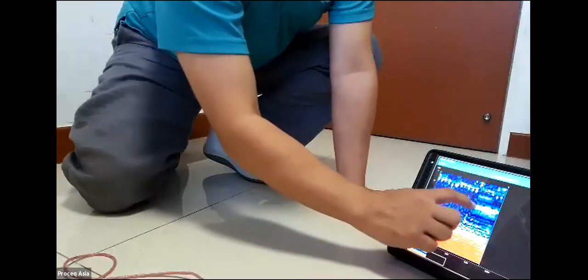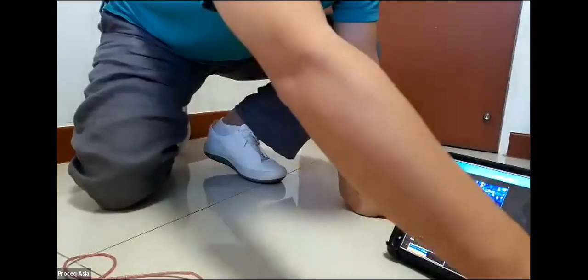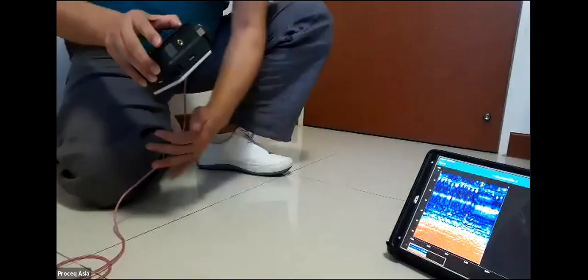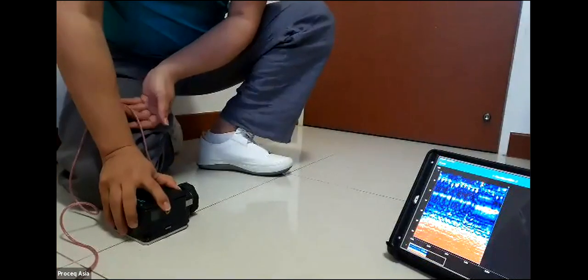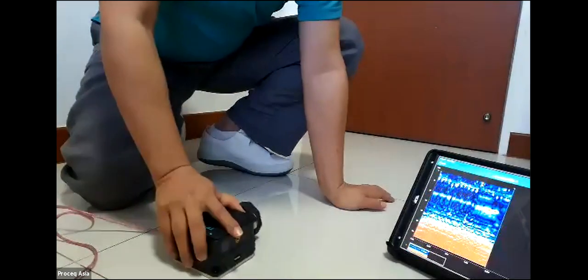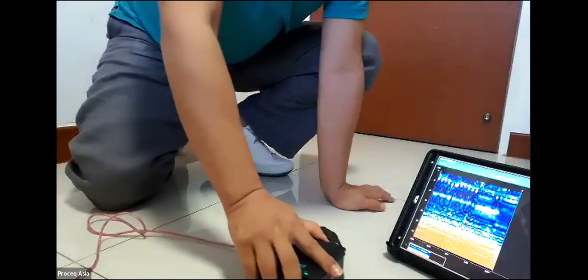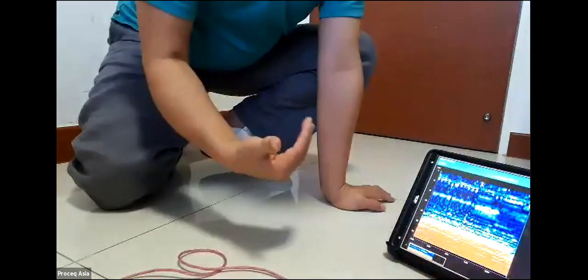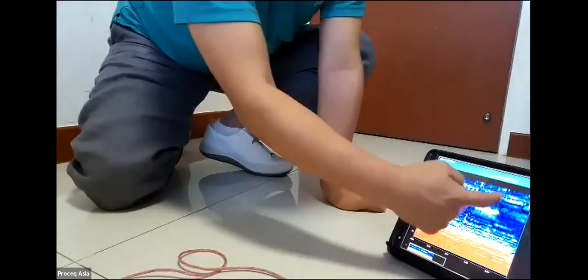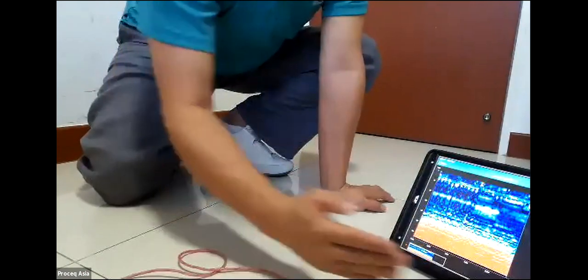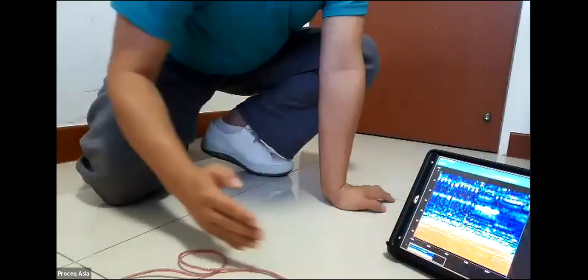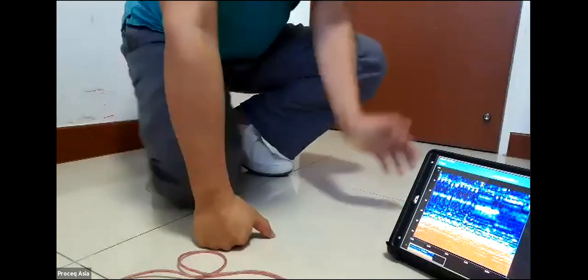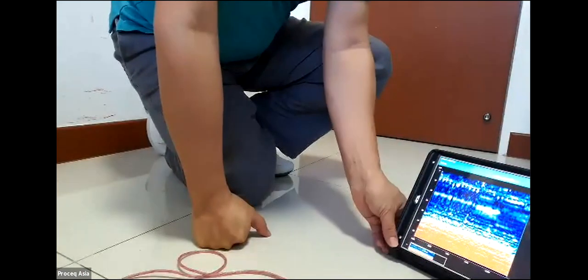Did you see that? Just now I couldn't see the back wall, but the first layer and second layer, which are perpendicular to my test location, are super clear. And for this line, why can't I see the back wall? For the second line, it's because a rebar along my measurement line blocks most of the signal. So this is my lab demo. Thank you, Sung.